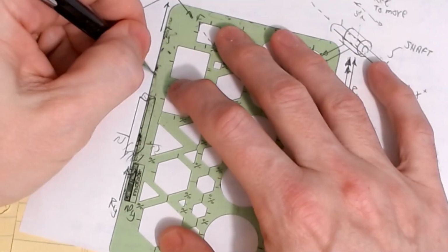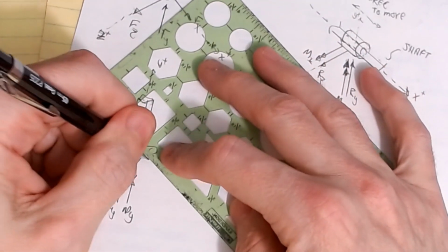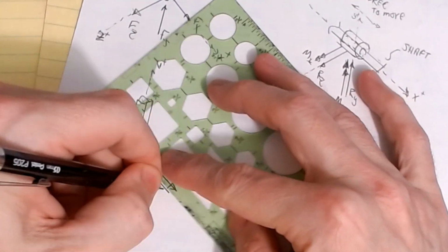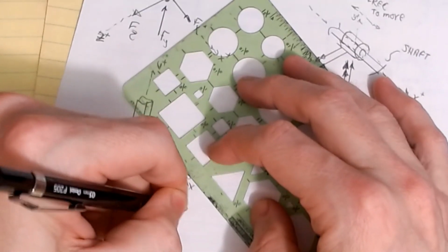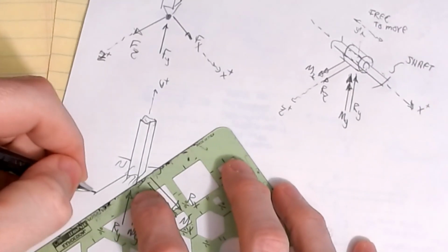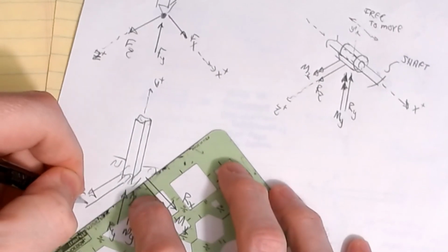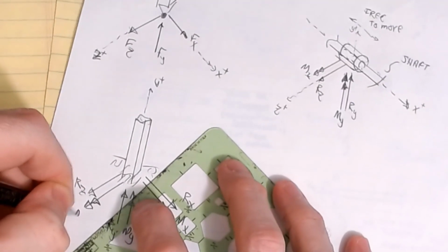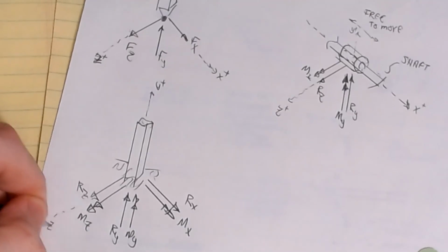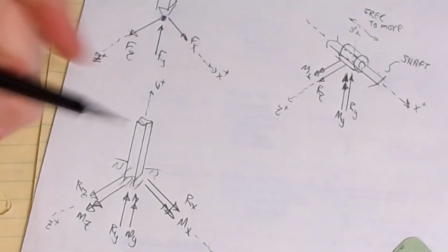Again, we're looking at our y-axis this way, and then we would have an RX and a moment about X. There's my moment at X. And then likewise coming this way, there's my RZ, and then this one would have an MZ that looks like that. Again, we're assuming Z positive this way, Y positive up, and then X positive that way. This is a full fix.